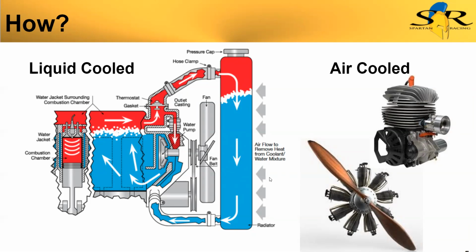And then also liquid cooling enables us to control the temperature more precisely, where in an air-cooled engine, the temperature is going to fluctuate a lot depending on the power demand. Air-cooled engines are often lighter than liquid-cooled engines, though, as a caveat. So I'll throw air-cooled engines in there for our Baja brothers, but for most of this, we're going to be talking about liquid cooling.